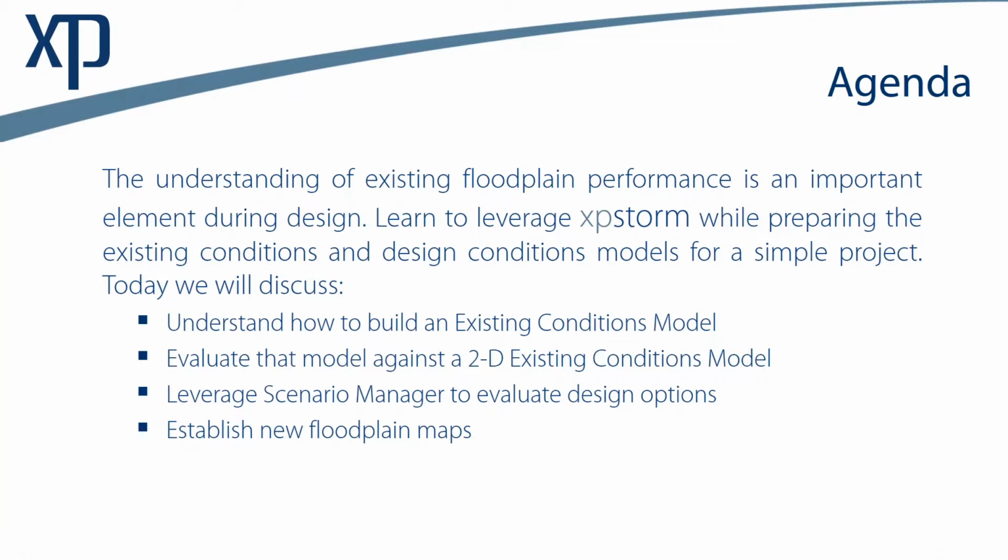Thanks, Nicole. Thank you for joining today's webinar. As Nicole indicated, I'm going to present a little bit about a project and talk about how to use xpstorm to evaluate the existing floodplain limits, and then how to explore the resulting proposed floodplain limits within the context of a design. In this case, it'll be a culvert underneath a road, but we want to explore how to build that existing conditions model. We want to explore really that two-dimensional analysis of that floodplain. In many cases, we might use a tool like HY8 or HEC-RAS to analyze the culvert itself, but in this case, we want to focus on the floodplain.